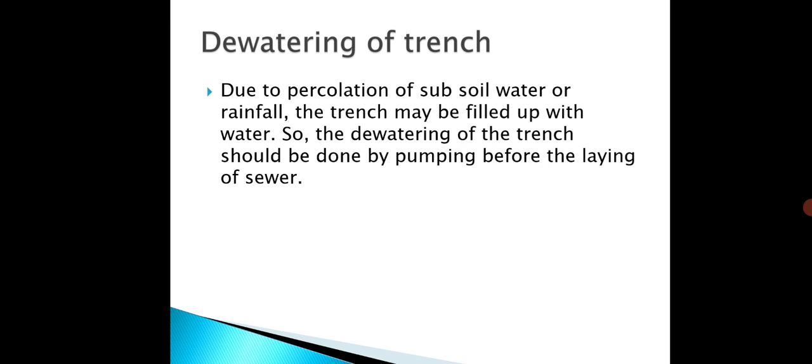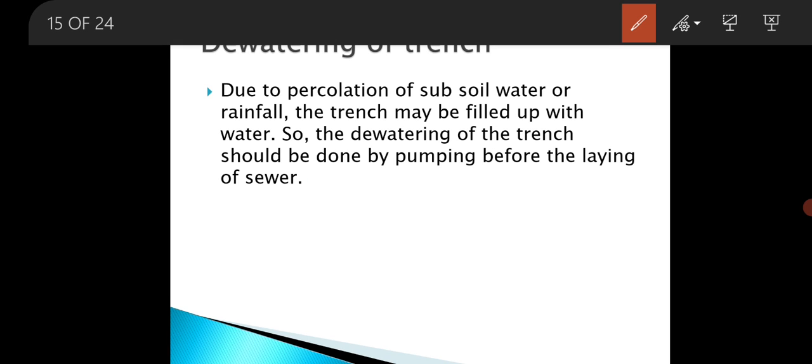Then after bracing, the next process is dewatering of the trench. Sometimes, due to sudden rainfall or due to percolation of subsoil, the trench may be filled up with water. So it is required to dewater the trench, and it should be done by pumping.